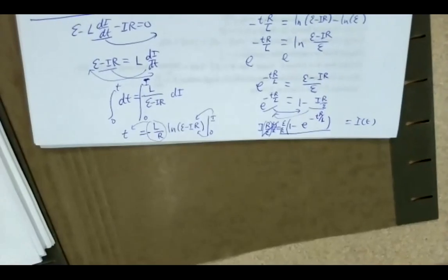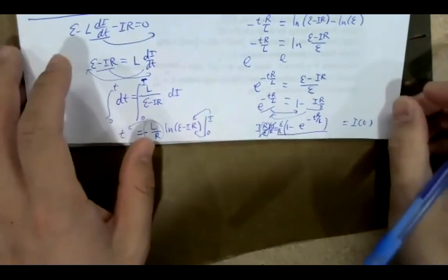For a capacitor, when you start charging, the current starts from the maximum and then decreases down. Okay. All right. But let's take a look at this example here. It says, how much time does it take for the current in an RL circuit with R equal to 130 ohms and L equal to 68 millihenry to reach half its final value? So we're looking at current and then looking for time t.